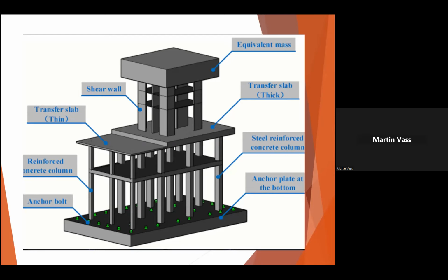There's a thick one and there's a thin one. So what happens, with the transfer slab over those parkade columns, you can put any load above and any spacing of columns you want above that. That would then transfer the load from the building down through those columns and down into the piles. So that is how you do a basic engineering study of how you do a building.